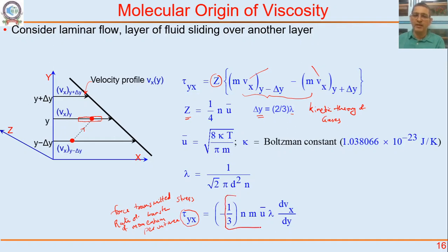And then this we had defined as the molecular viscosity, and this was our strain. This was like the driving force for momentum. So imagine that rho Vx is momentum per unit volume, okay? And then dy is how rapidly or how fast this gradient exists, or what is the driving force for momentum over this length delta y.